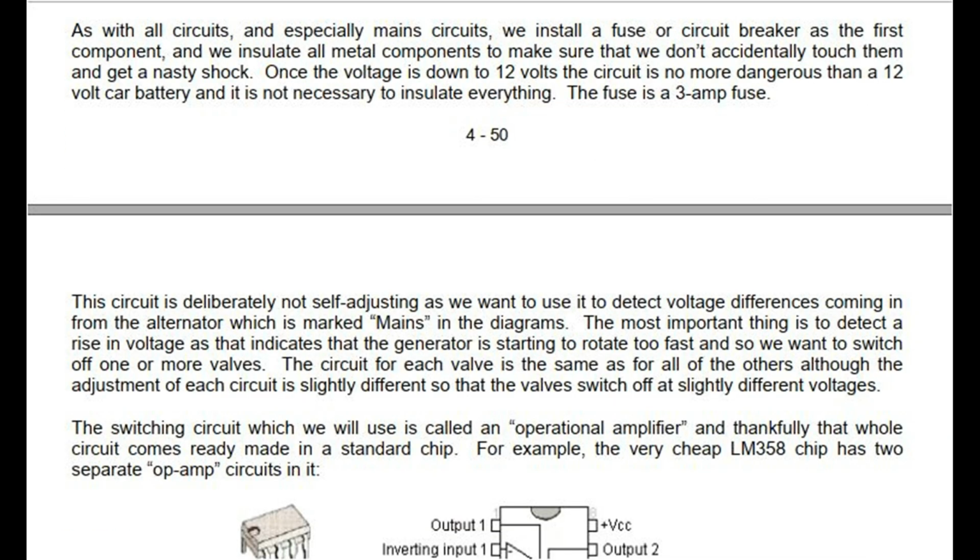As with all circuits, and especially mains circuits, we install a fuse or circuit breaker as the first component, and we insulate all metal components to make sure that we don't accidentally touch them and get a nasty shock. Once the voltage is down to 12 volts, the circuit is no more dangerous than a 12-volt car battery, and it is not necessary to insulate everything. The fuse is a 3 amp fuse.